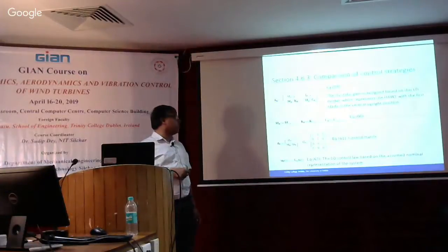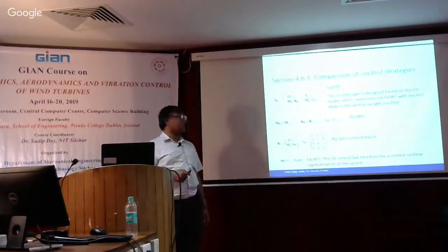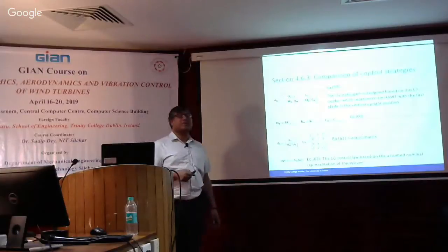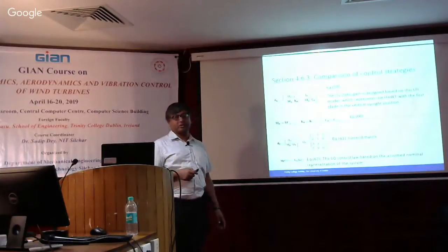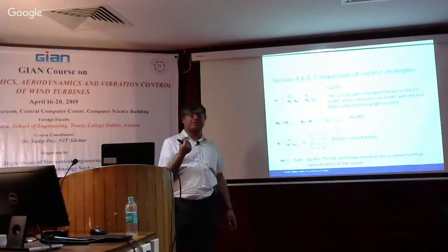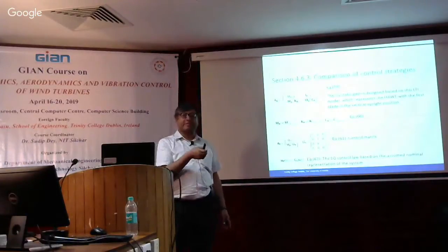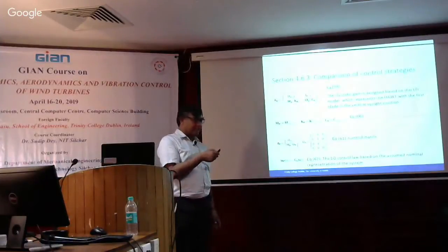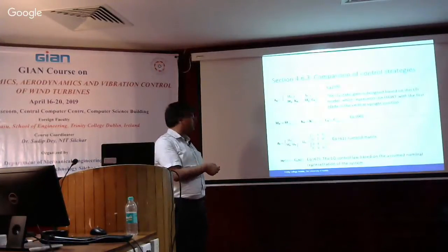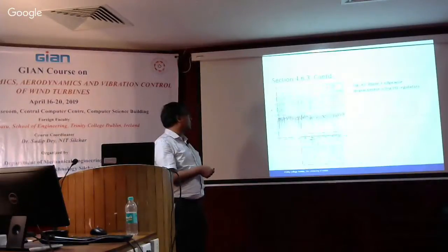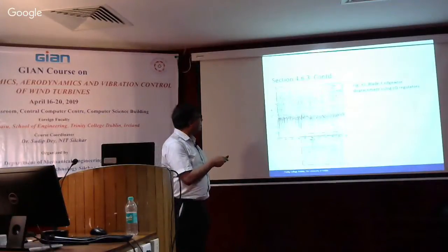Now, we did also compare with other control strategies, like one where we use direct velocity feedback. It's another way. What we do is measure the velocity and feed back something like velocity, and that actually adds damping to the system. And we found that our previous LQR is better than velocity feedback. And also, we compared with our MBC-based LQ problem, the nominal LQ problem.